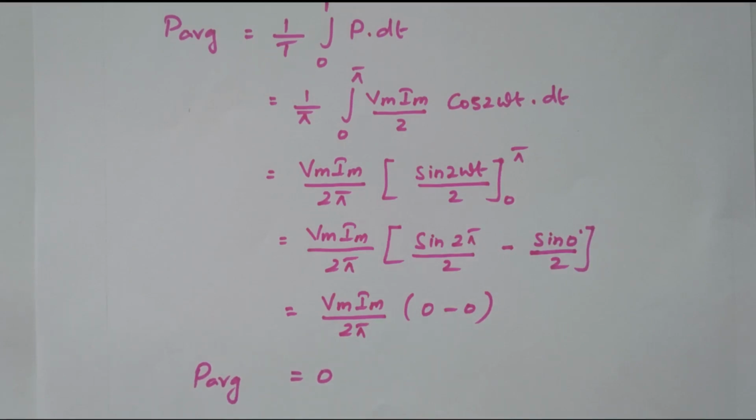So in this video we discussed the behavior of current and voltage when AC voltage is applied to the capacitor. We identified that current is leading by 90 degree. We analyzed the two equations, and from the current and voltage equations, we identified that current leads by 90 degree. Also we calculated the expression for instantaneous power and average power. Thank you.